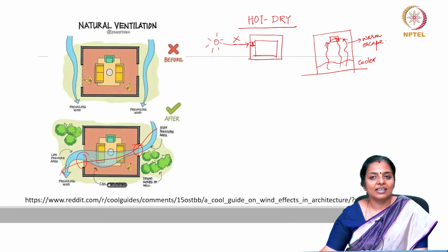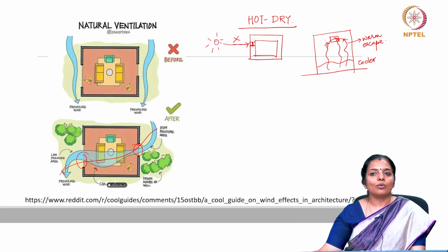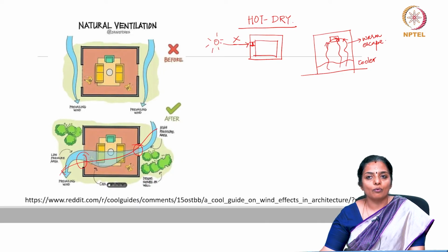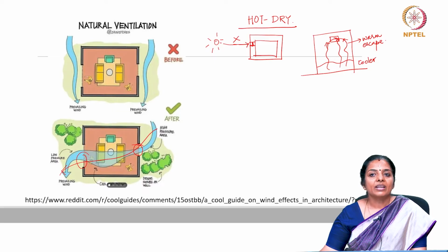In such a case, the door acts as the inlet. The two windows, now outlets, would lead to a good airflow. If the total area is greater than the door, then the air velocity would be increased. Only if one external or free wall exists, it might be preferable to provide two windows on it rather than one. This would improve the ventilation when the air is incident angularly on the windows.